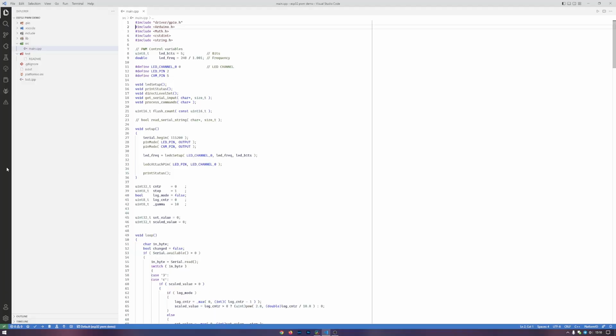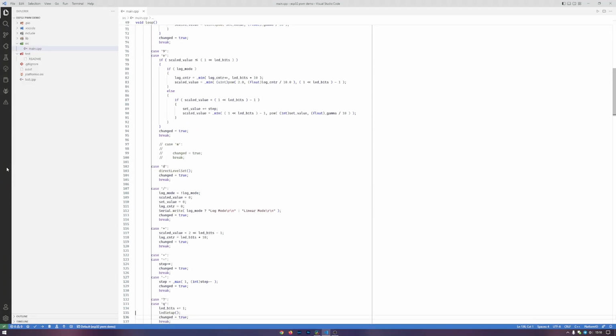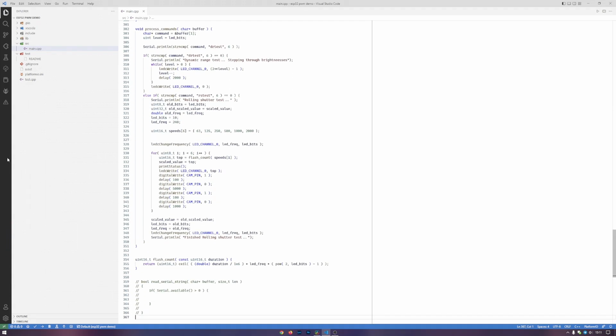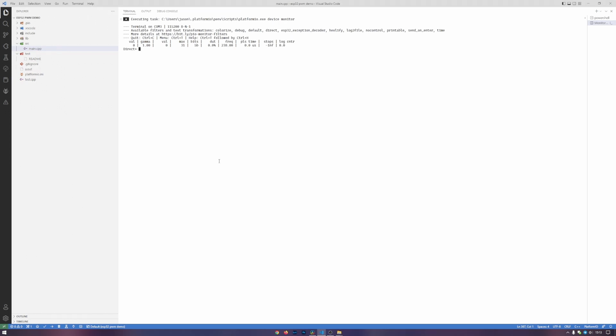This is especially good for this task as one, they're cheap, at like $10 or something like that for a development board, and two, the ESP32's LEDC, or LED control module, has an incredible range of capabilities when it comes to doing pulse width modulated control. Doing the actual toggling is a beefy N-channel MOSFET transistor that is massively overkill for what it's being asked to do, but that also means that it never actually gets hot. Driving all of this on the software side is PWM control software that I wrote. It is more complicated than it technically needs to be because I wanted to be able to interface with this from my computer and make adjustments to frequency and duty cycle and all of that. But technically, if you wanted to put something like this together, you could do this with an Arduino and like 3 or 4 lines of code, or an ESP32, which you can also program with the Arduino programming and development environment, and 3 or 4 lines of code.